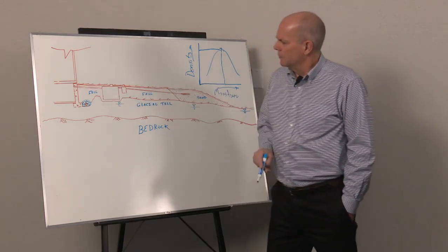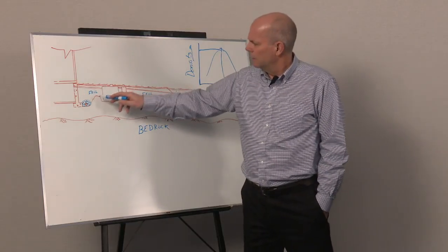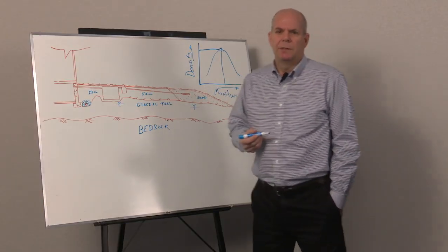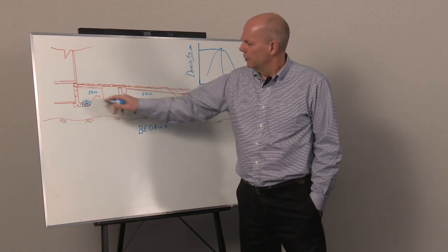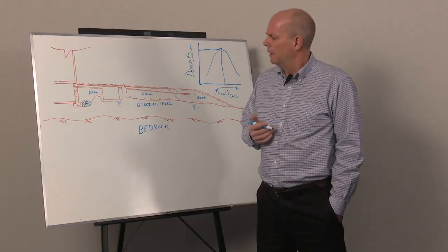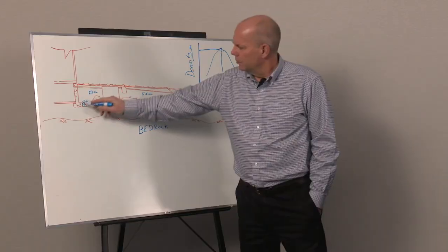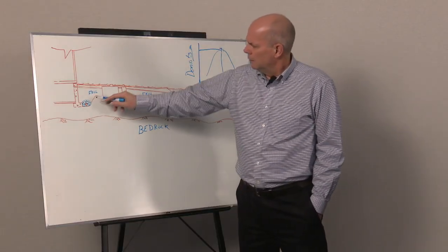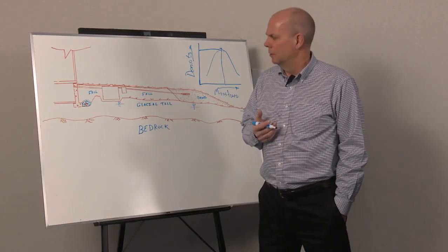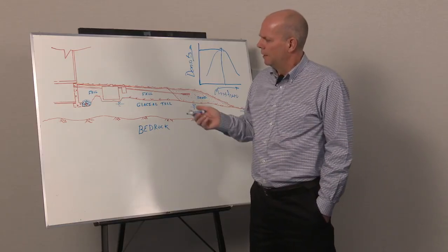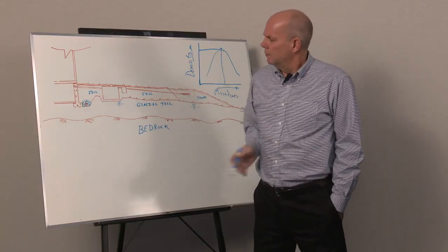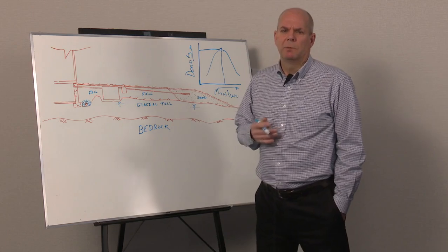As the effluent pipe is leaving the house, we're crossing over typically, as a minimum, the foundation backfill. And most foundation backfills would consist of a perimeter drainage system that would be clear stone gravel wrapped in geotextile. If that's done properly, there should be no issues associated with that drainage system. The fill on top of that would likely be excavated material from the foundation excavation that had been stockpiled. That stockpiled material, like I said, if it's in a clay-based material, it'll get dumped back against the wall a lot of times without any compaction.